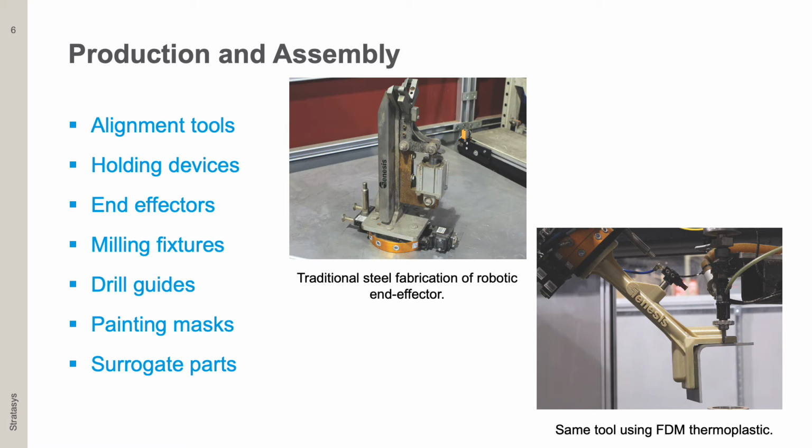The result was a 95% weight savings, or reduction by 32 pounds, and an 85% turn time savings, which equated to 17 days saved. Additionally, the 3D printed tool incorporated internal vacuum channels, eliminating the need for external vacuum hoses in the vicinity of the cutting water jet. The lighter tool made it very easy to handle and install on the robotic arm compared to the steel end effector, and also meant less wear and tear on the robotic actuator motor.